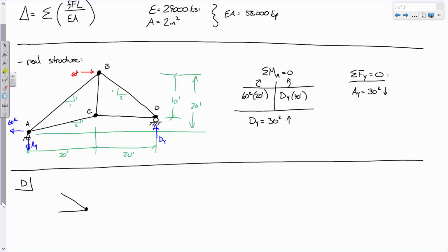All right. So here's this. This is 1 to 2. All right. And you're going to notice how I do my method of joints analysis pretty quickly, because these slope ratios are pretty simple. Now, are there any loads on joint D? And it's 30 kips going up, right?